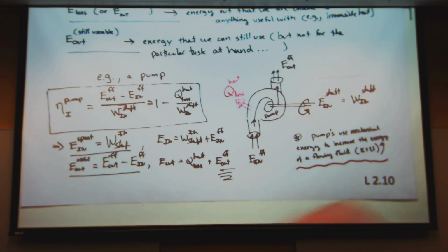It's to move liquid, to increase its kinetic energy or potential energy, so we can overcome a potential barrier, right? To bring a control volume of liquid from here to 1,000 meters above my head requires energy, because I have to work against gravity. So I have to increase the energy of that control volume in order to overcome that. And so you just use a bunch of control volumes connected to each other, and the bottom one has the highest pressure, and then it overcomes that.